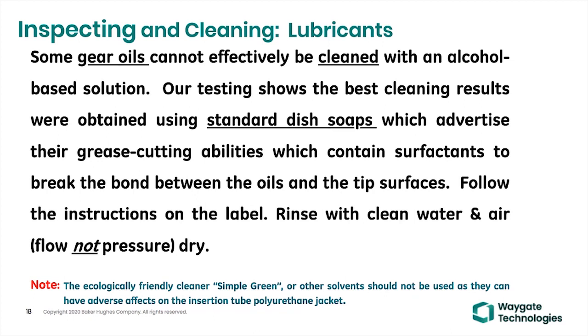So people have asked, well, can I clean them with a keyboard cleaner, a can of keyboard air? Sure. Just don't stick the nozzle in the backside of the tip, push the trigger, and that air pressure is going to blow the O-ring out. Hold separation between the tip of that nozzle and the back of the optical tip adapter and air dry it.